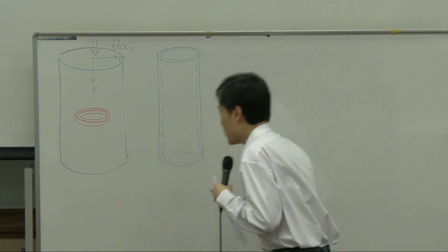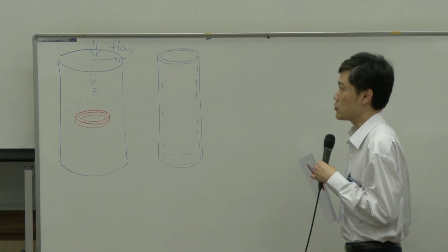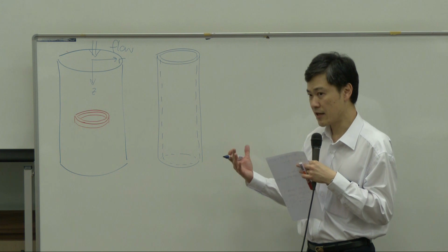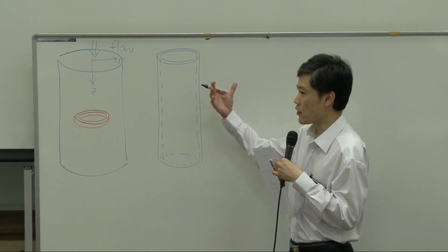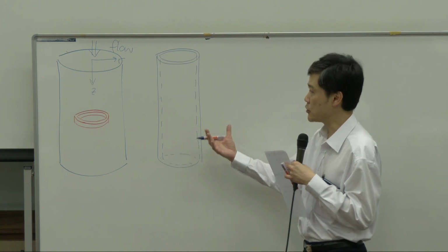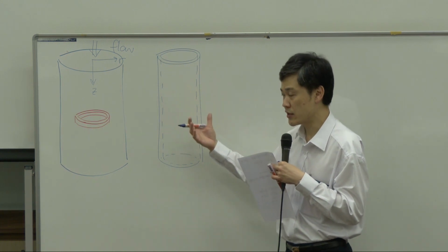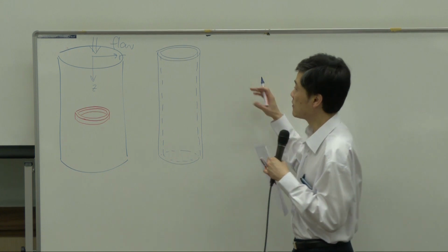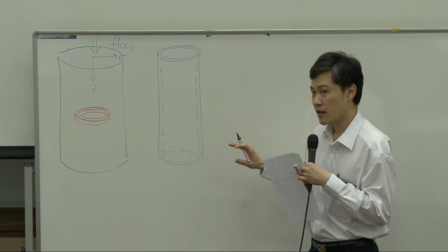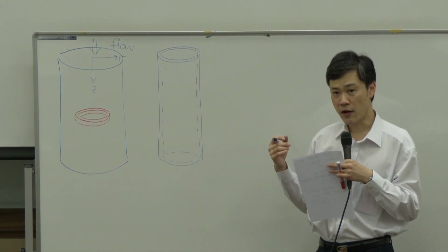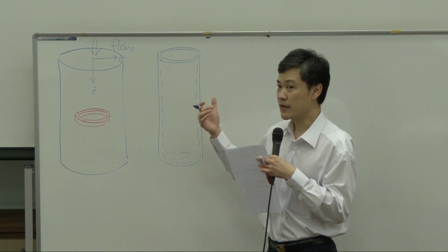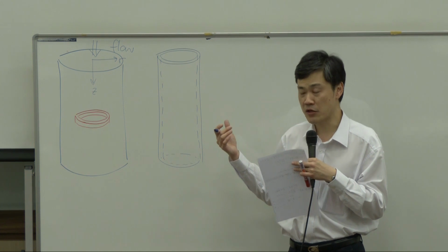Okay, so the next question would be how to start the equation. Once again, we have momentum transport as well as energy transport. If we start with momentum transport, we have to assume that temperature changes do not affect physical properties such as density and viscosity. On the other hand, if you want to start with temperature or energy balance, you have to assume that the convective transport does not affect that much.